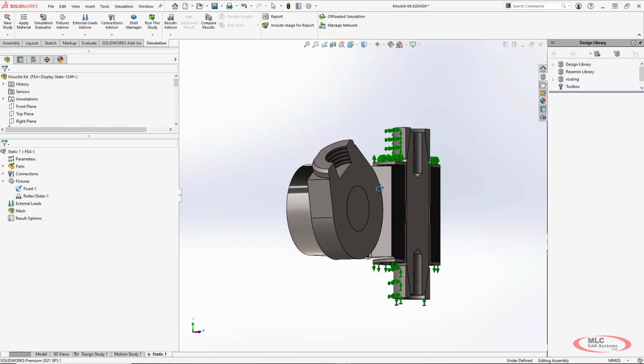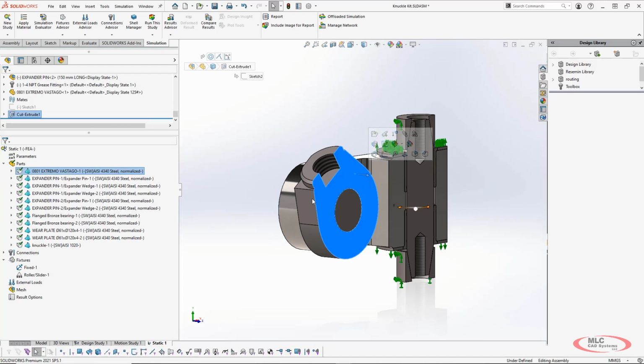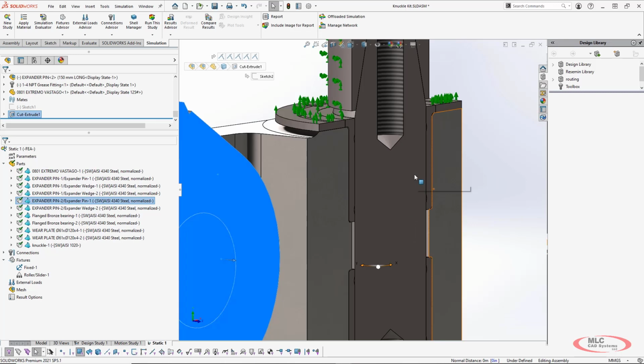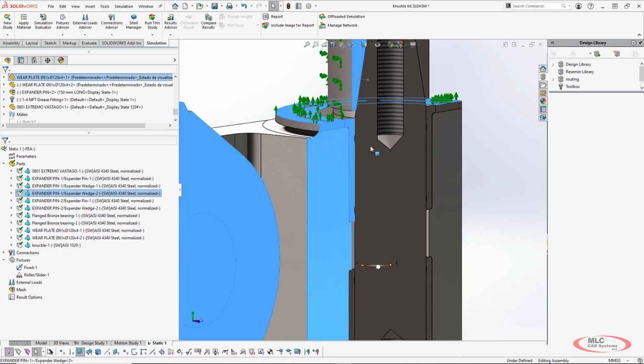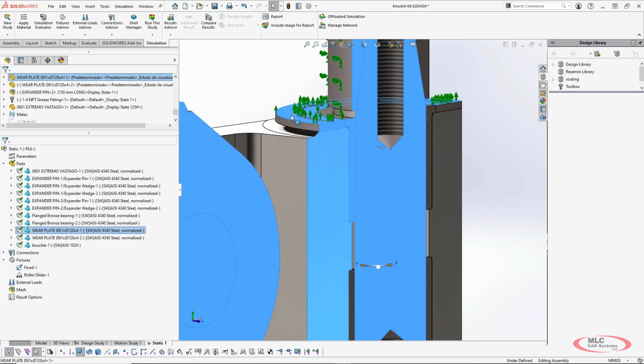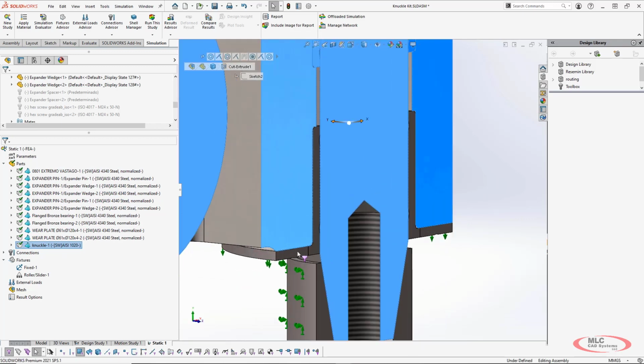Now the last constraint that we need to do is the symmetry constraint. So we need to select all these faces that lie on the symmetry plane to do that. So I'll go ahead, I'll just filter for faces just to make it quicker. If there were many more faces than this, I'd probably use some selection managers to be quicker, but in this case, we're about at that number. I accidentally selected an extra one there. It's probably just as quick to just manually select them.